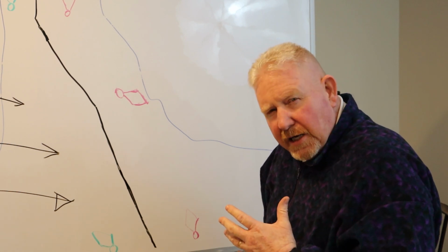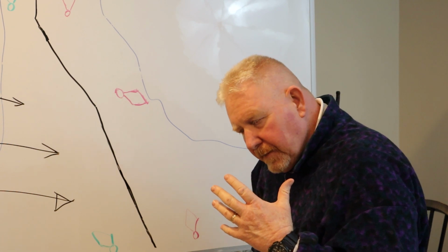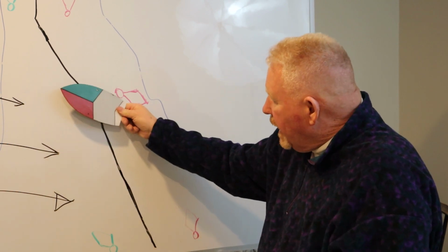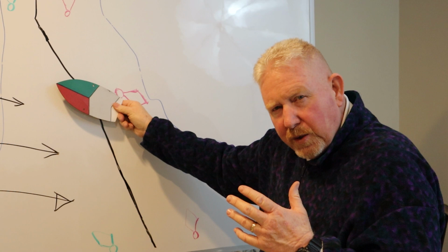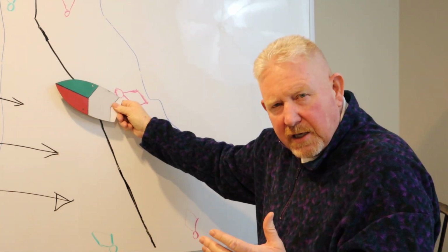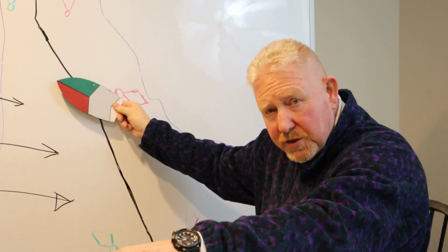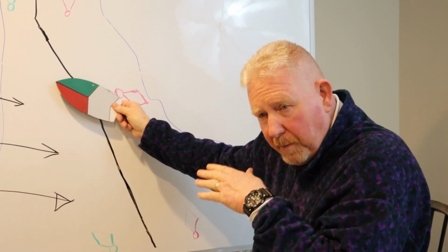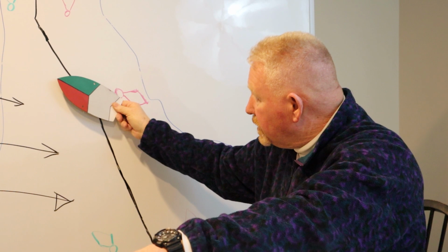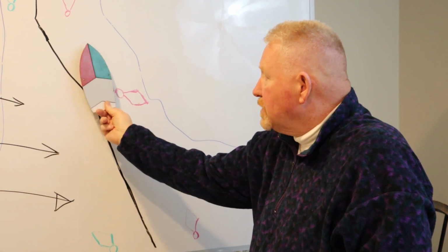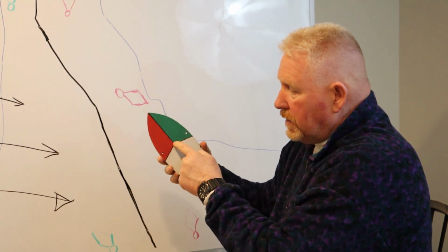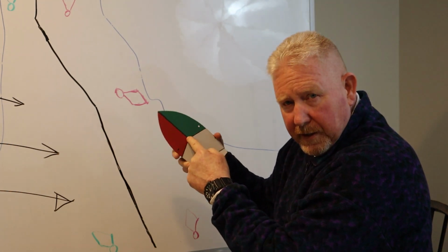We had this discussion, and I exercised my options. If I wanted to clear this buoy with my stern, I could have given a command like right full rudder, which, if I want my stern to go to the left, the bow is going to go to the right. Remember we talked about a boat being on a pivot point?